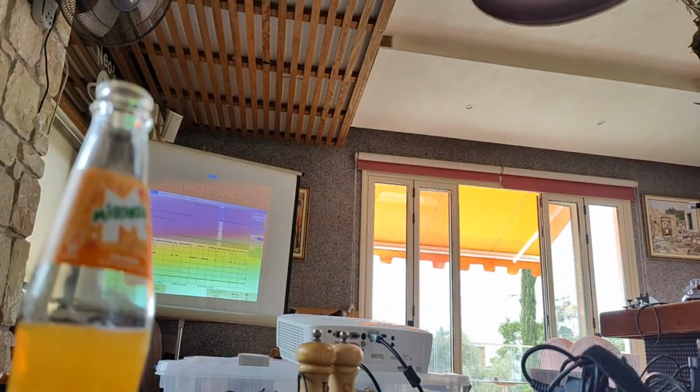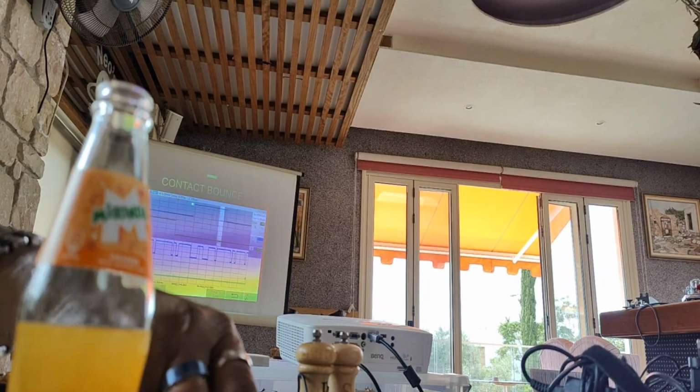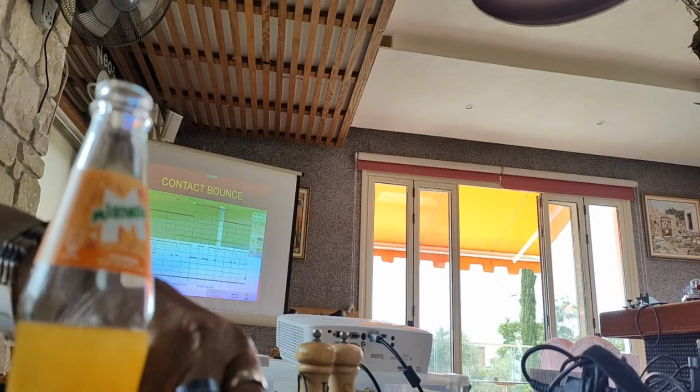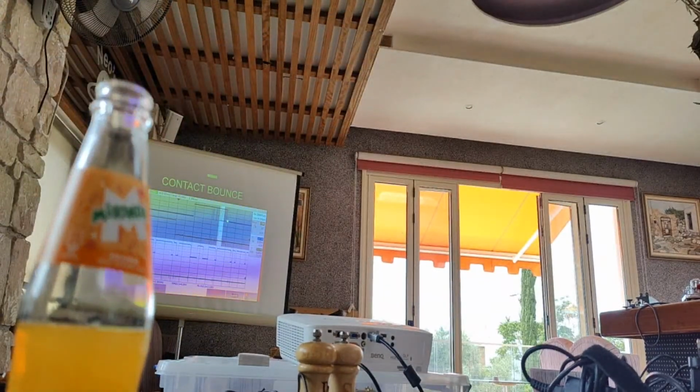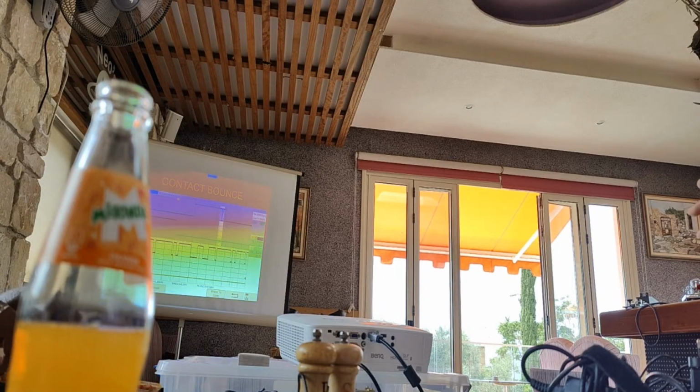As I say, nearly 10 milliseconds before anything happens. And then suddenly the armature starts moving. So this goes up to plus 12 volts, and it accelerates across the contact gap, hits it, and starts bouncing. This highlighted section here is expanded on the bottom trace, so you can see what's happening.